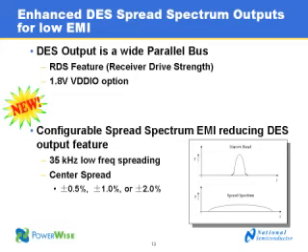And then the configurable spread spectrum, thanks Alex for leaving that one to me. So again, we talked a little bit about this before, and this concept was introduced in the previous discussions. What we're doing here, to get into a little bit more detail, is the clock typically operates at, let's use as an example, 65 megahertz. So what you would want to do, if you're spreading the spectrum, is move that a little bit by a few percent. In this case, it's plus or minus 2%. So a slight variation of the frequency over time at a very low modulation rate.